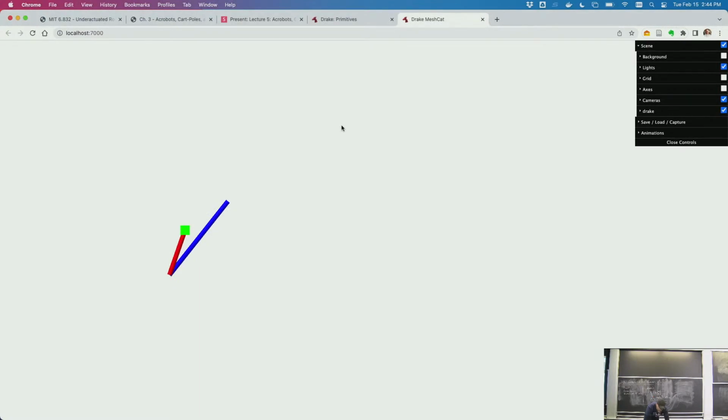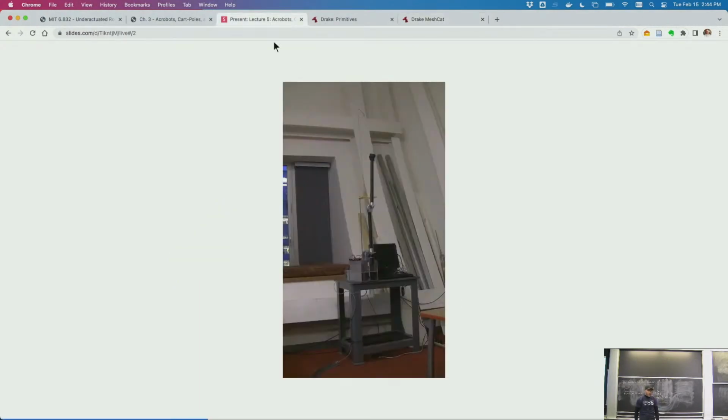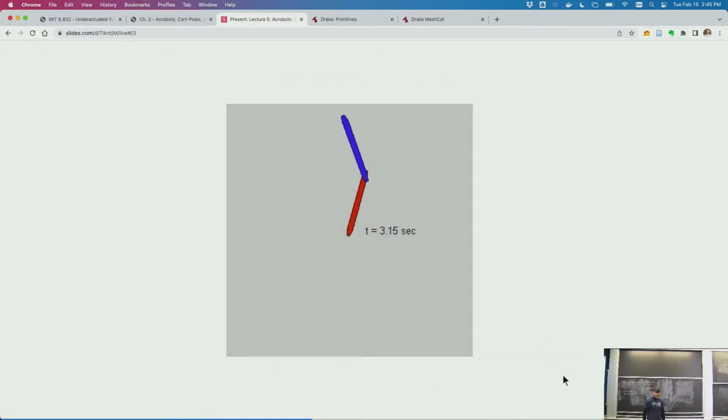Now, despite missing a motor, you saw it slowly swing up in the video, but you can actually do pretty awesome swing ups too. This is the trajectory optimized swing up of the Acrobot under some torque limits, and we'll have that solution available in another notebook soon. OK. It's also, if you note, stable at the top. The real robot stayed up at the top, and that's pretty cool that it can stabilize that two-link system even though there's no motor there. You would think that it would fall down and that this motor wouldn't have enough ability to stabilize that, but actually it does, and we'll see that in detail today.